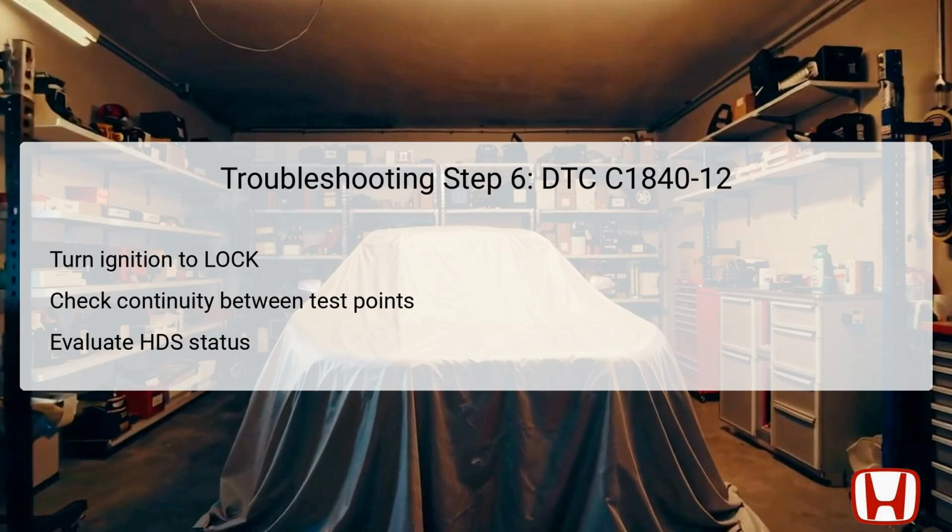If continuity is evident, it suggests that the wiring is intact, and further options may include updating the real-time AWD control unit's software to ensure the latest version is installed. Alternatively, it may be necessary to substitute this unit with a known good part and recheck for errors.